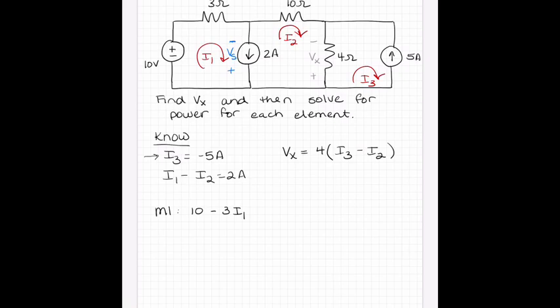So to finish this, moving from minus to plus, I will add Vs. I'm back to where I started. I can sum to 0. Okay, so when we have a current source shared between two meshes, we're going to have to label a voltage and it's going to enter into our equations. Mesh 2. I'm going to start with that current source. Now I'm moving from plus to minus through that source, moving in this direction. So I'm going to subtract that voltage.